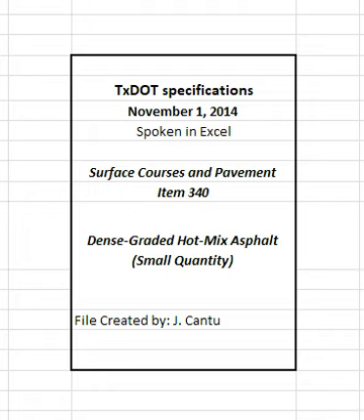4.4.2 Mixing and discharge of materials. Notify the engineer of the target discharge temperature and produce the mixture within 25 degrees Fahrenheit of the target. Monitor the temperature of the material in the truck before shipping to ensure that it does not exceed 350 degrees Fahrenheit, or 275 degrees Fahrenheit for WMA, and is not lower than 215 degrees Fahrenheit. The department will not pay for or allow placement of any mixture produced above 350 degrees Fahrenheit.